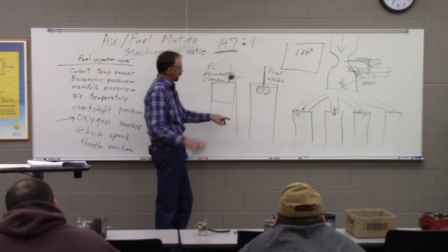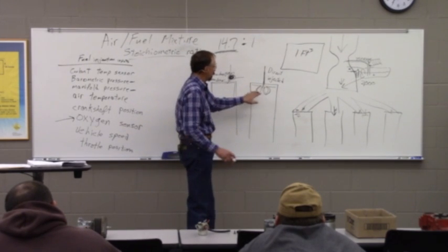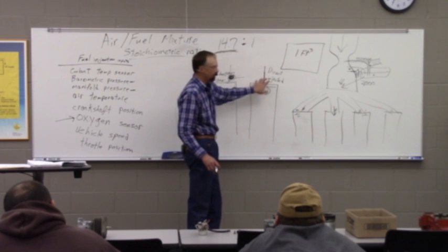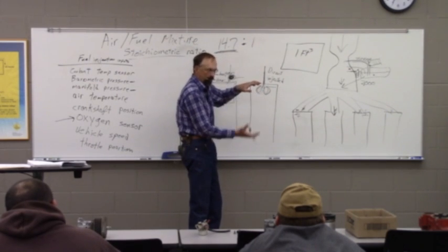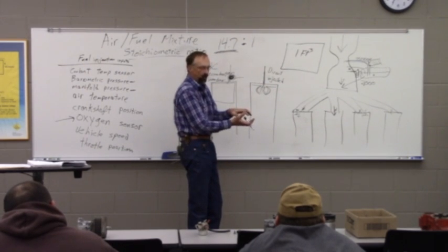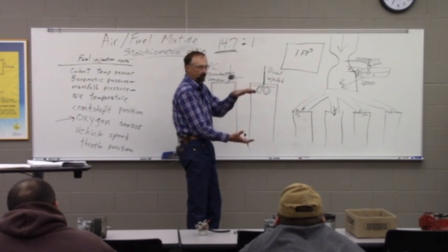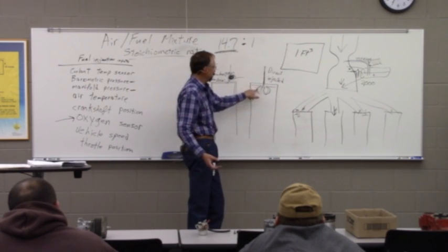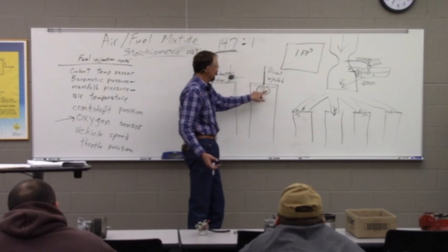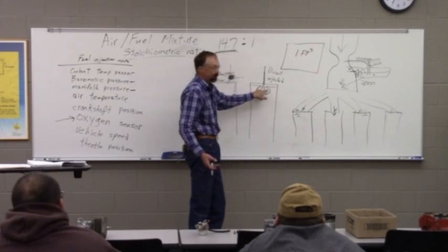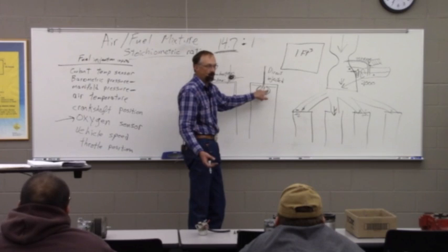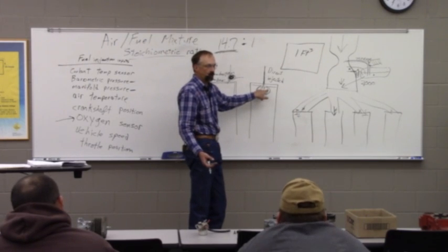The way it flows from this chamber into the main cylinder as that piston's starting down and the flame travel is propagating throughout the air-fuel mixture, it makes much more even pressure, and it makes better power and less emissions because we've got less of what's known as quench area.